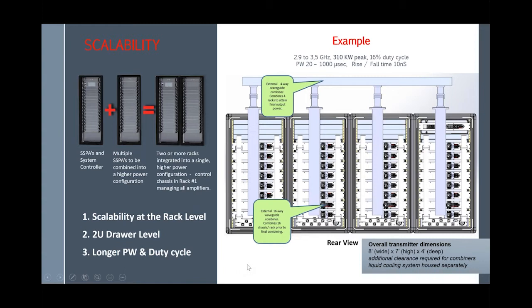So, down the road, we could provide you with a software firmware change that gives you longer pulse width and duty cycle. And tell me if I'm right or wrong about this. You still have to trade off peak power for average power in that case. Yes, the issue is the following. The longer the pulse, it approaches the amplifier to a CW operation, which means that you have to back off the power because the device cannot handle that.